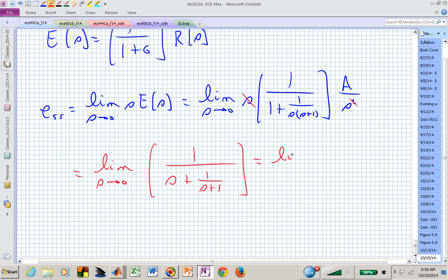But that's now the limit. If we didn't do it quite so quickly, that's now the limit. What's happening to this piece right here, the first s in the first term of the denominator, as s goes to 0? That goes to 0. But what's left is this 1 over s G of s. That's really what was left over, and we actually call that the velocity gain constant, K sub v, which is the limit as s goes to 0 of s G of s.